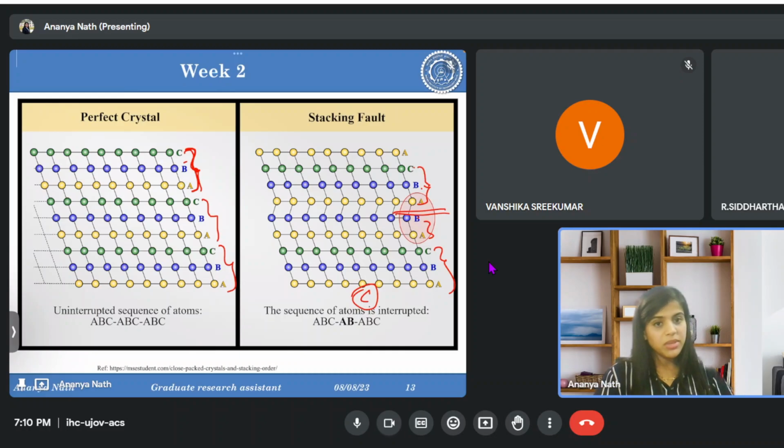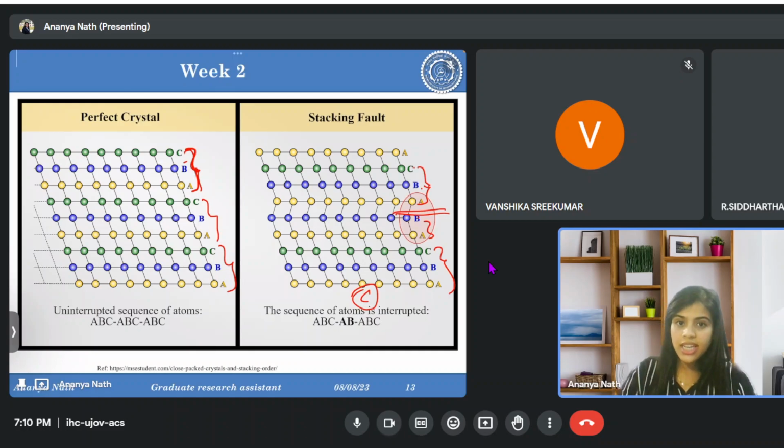Due to the missing plane, there will be some disruption in the dislocation, and if the dislocation has been divided into two parts, the Burgers vector for each dislocation will be different, due to which in between the two divided Burgers vectors there will be a place where the solid atoms generally feel safe or preferable to go and sit. So that stacking fault width is maintained.